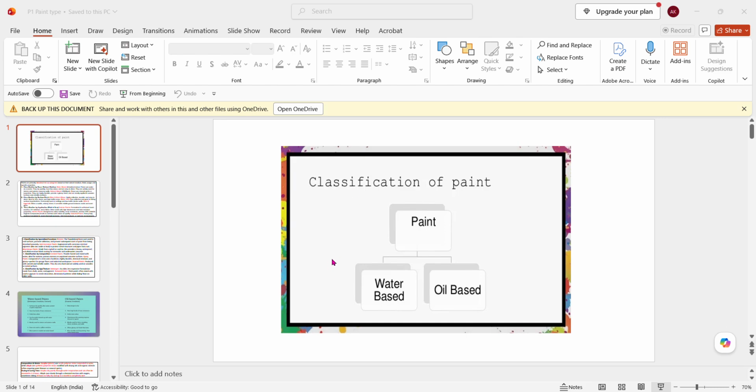Similarly, as per the field use, there are exterior paint and interior paint. The exterior paint means they are supposed to withstand harsh weather, UV protection meaning sun protection, dew, mildew, etc., and fade resistance. And interior paints means designed for color stability, scrub resistance, and low VOC, meaning volatile organic compound, to maintain safe indoor air quality. That will maintain the air quality.